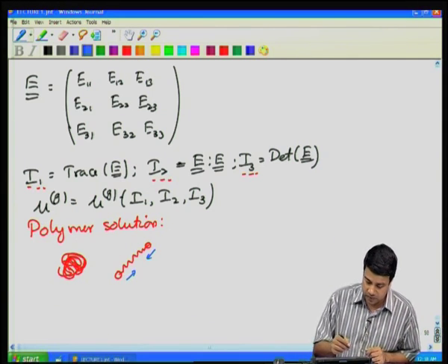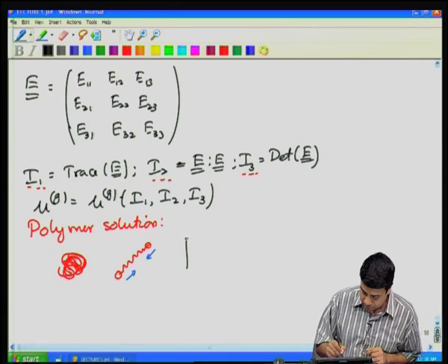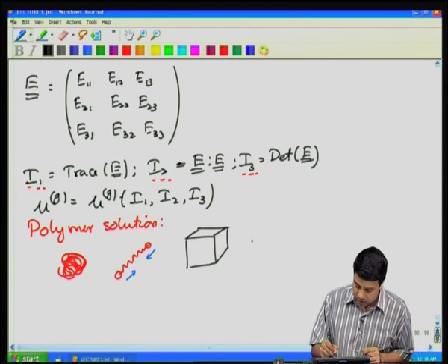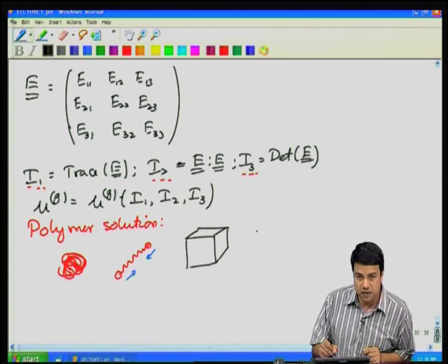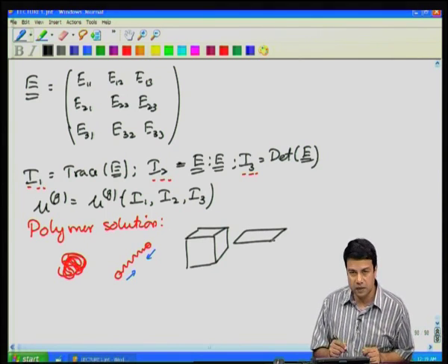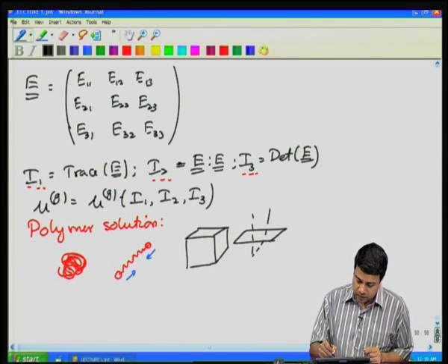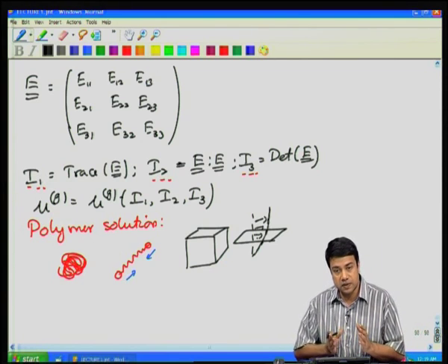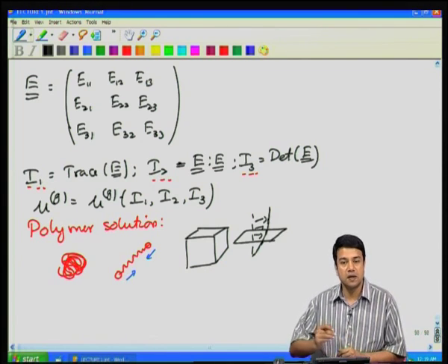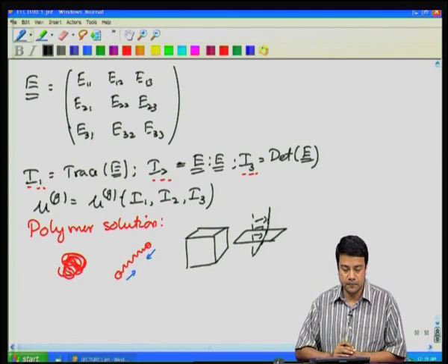Okay. So, for example, if I have a differential volume, okay, if I take one particular surface of this volume, there is of course a transfer of momentum due to the mean fluid velocity across the surface. There is also a transfer of momentum due to the velocity gradient across the surface, fluid momentum diffusion.